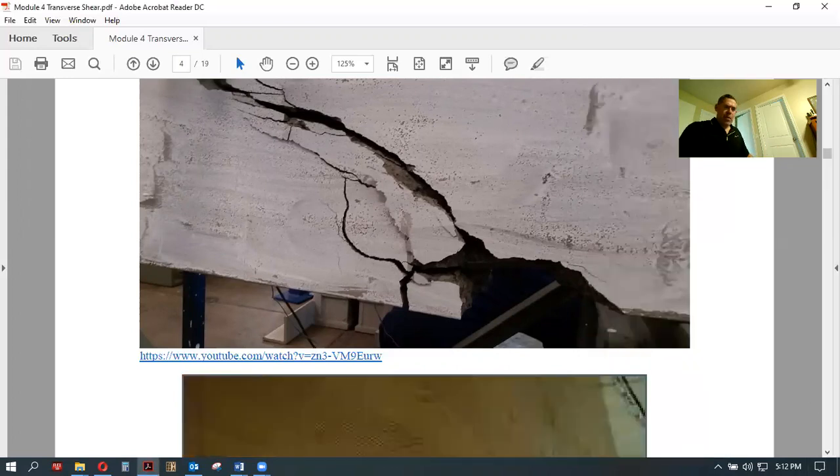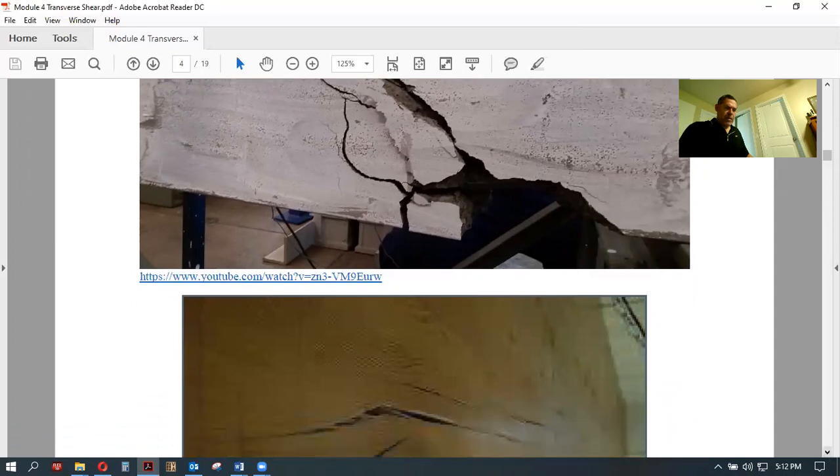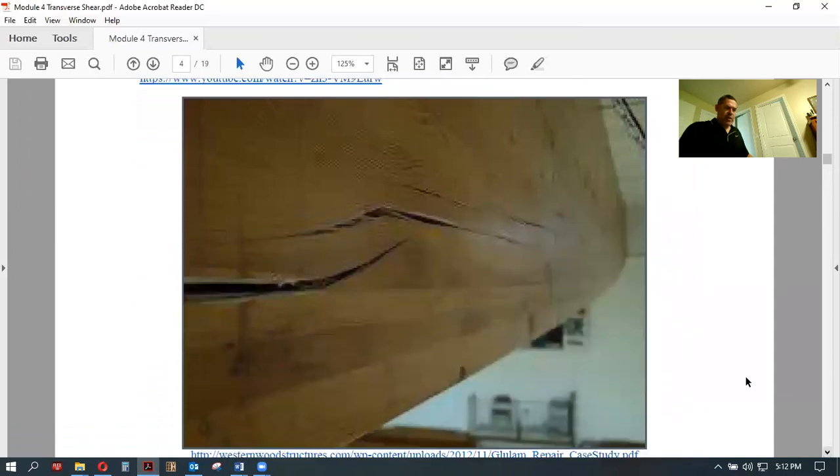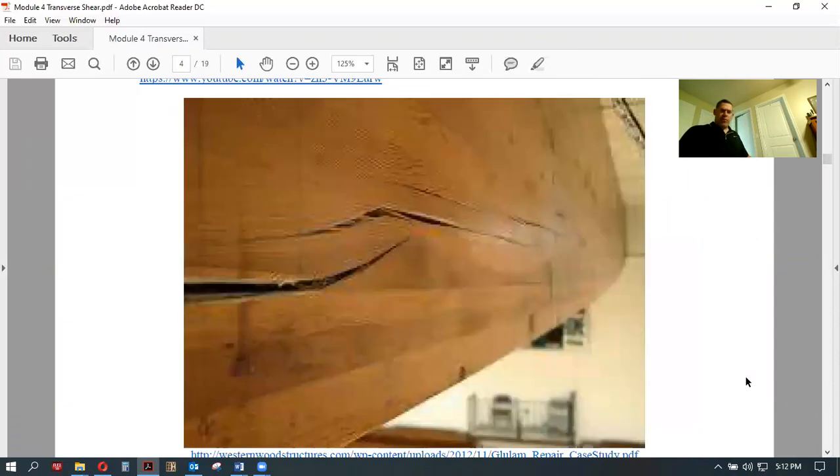Okay, now the other part that I want you to take a look at is this glue-lam timber beam down below. Here you have horizontal layers of 2x8s or 2x6s, 2x4s, that kind of thing, all laid up horizontally, and then they are bonded together through an epoxy. It's laminated, and because it has multiple layers and is glue laminate, it's really more of an epoxy than a straight glue, right?